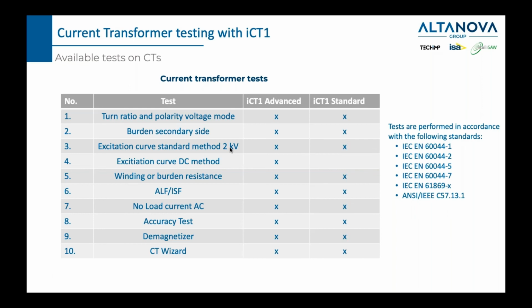And of course, since it is the latest product when it comes to this type of testing equipment, we follow the older 60044 standards, and the newer 61869 standard from IEC. We also comply with IEEE C57.13.1. So this is important to mention. We do test according to standards, using the signals which are prescribed in the standards.